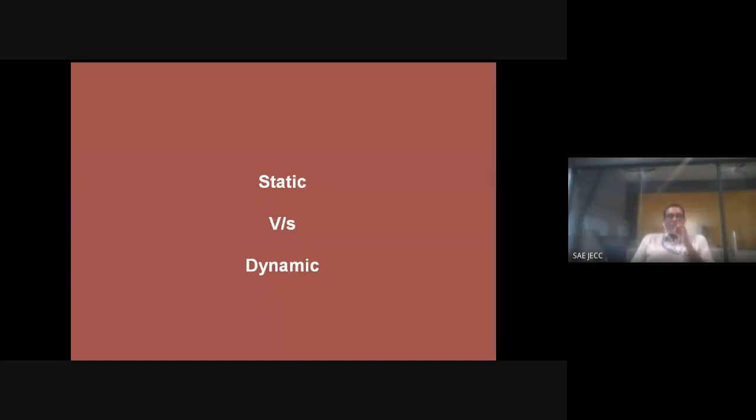What is dynamic condition? The force is fluctuating. Even though the magnitude of the force is much less than the maximum permissible limit, if it is operating at a particular frequency that coincides with the natural frequency of the system, it is capable of producing disaster, or it may damage the structure. So it is not only the force that decides the stability of the system; the level at which the force is acting and the nature of the fluctuating effect decide the stability of the structure.